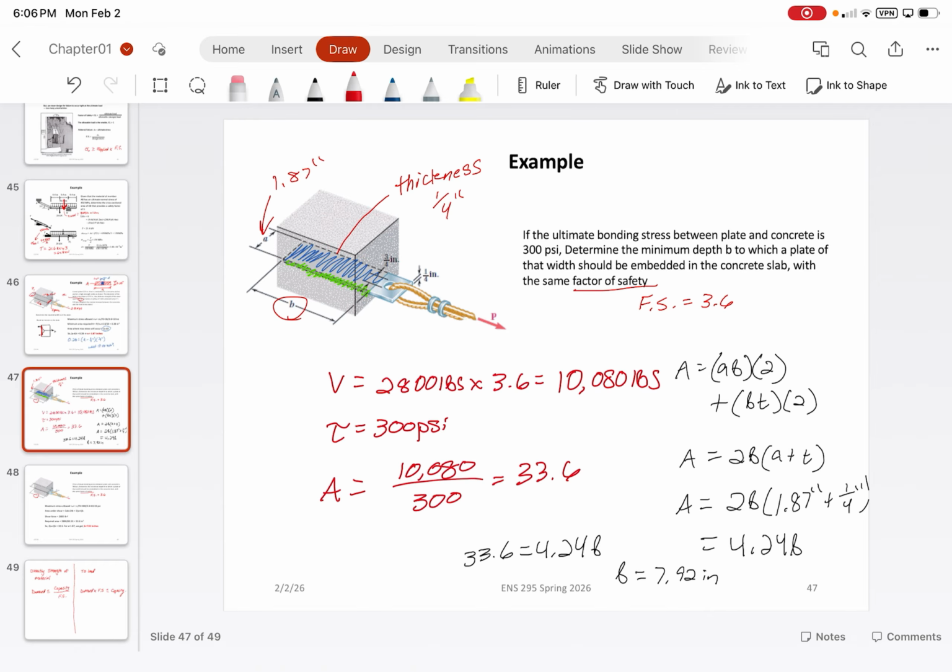If you're calculating what the capacity needs to be, that would give you the ability to look on a product data sheet and determine, okay, this is the strength that I need. For example, if you compute you need a steel that can carry 30 KSI, and you find a steel that can carry 60 KSI, you're good.